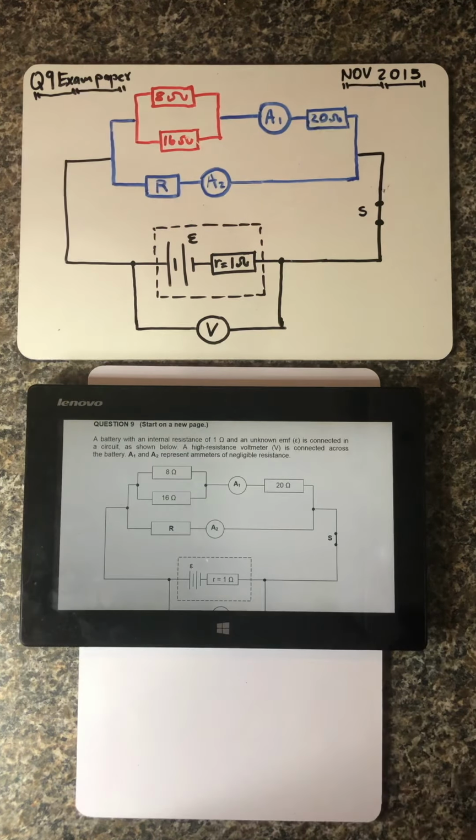It means the voltage which is going to supply anything connected to that circuit will be less than 3 volts. Why? Because part of that 3 volts will be resisted by that 1 ohm resistor. So the 1 ohm resistor will resist some of the voltage, it will retain some of the voltage within that battery. The other thing that I want to talk about is that this 3 volts is referred to as the EMF.